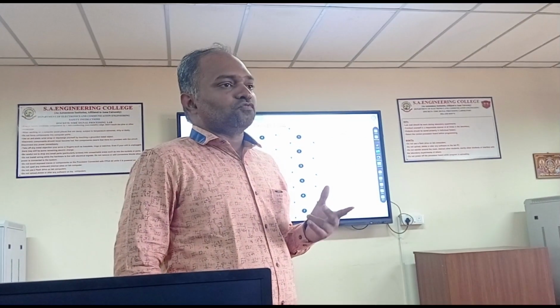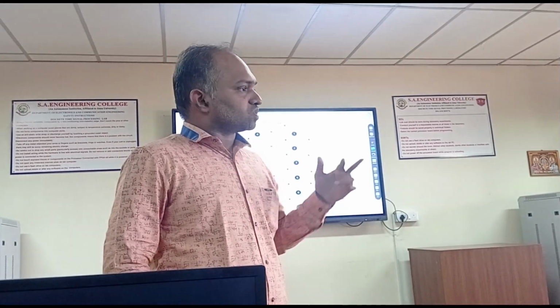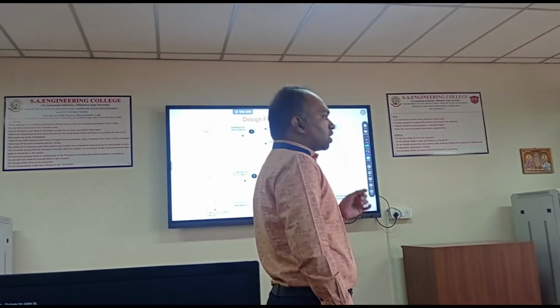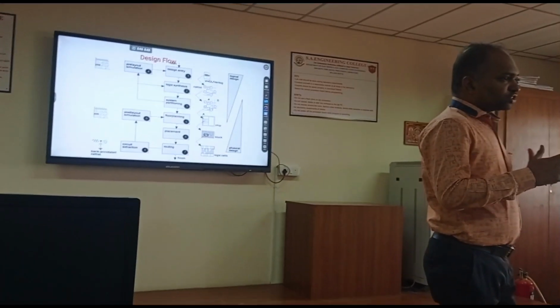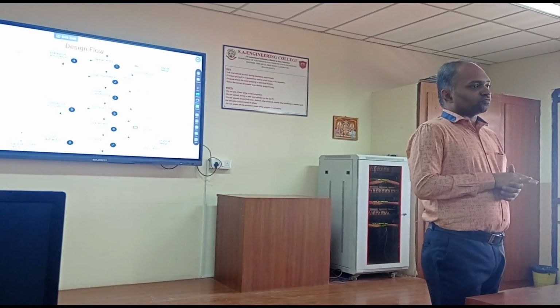No, no. For an AND gate also, if you give 1 and 1 as input, what will be your output? 1. For an OR gate also, 1. But whether it is actually performing an AND gate operation or OR gate operation, how will you confirm? So this simulation information is not sufficient to justify the design. That's a basic problem of digital circuit simulation.